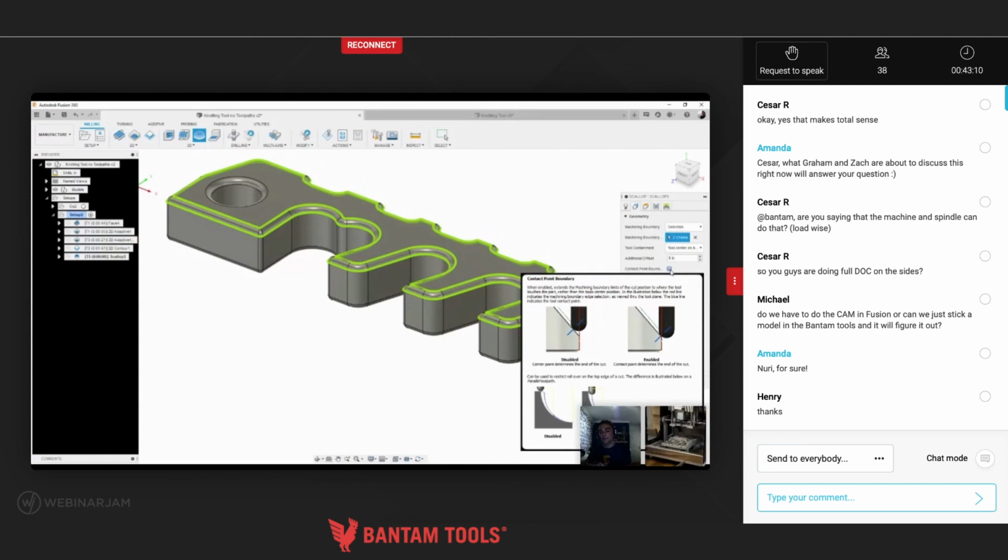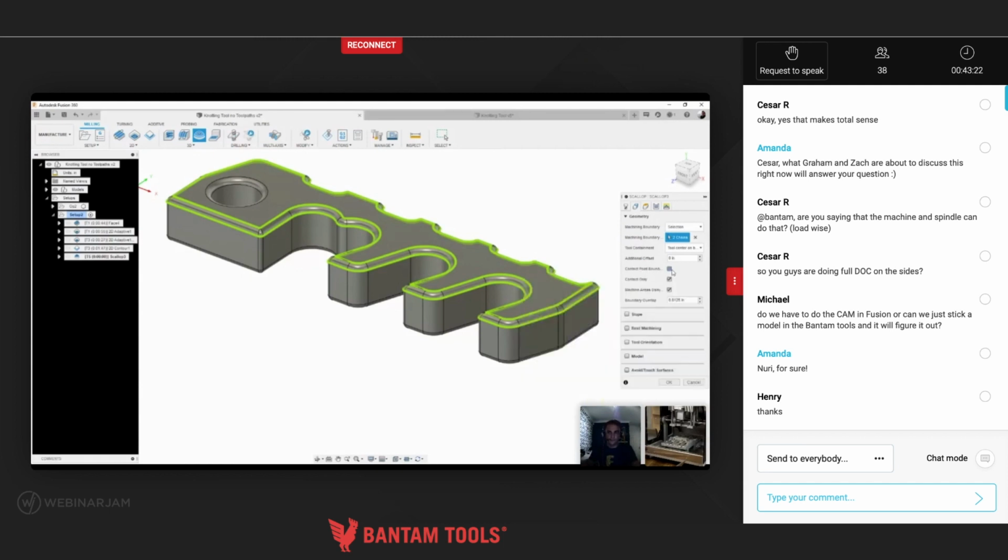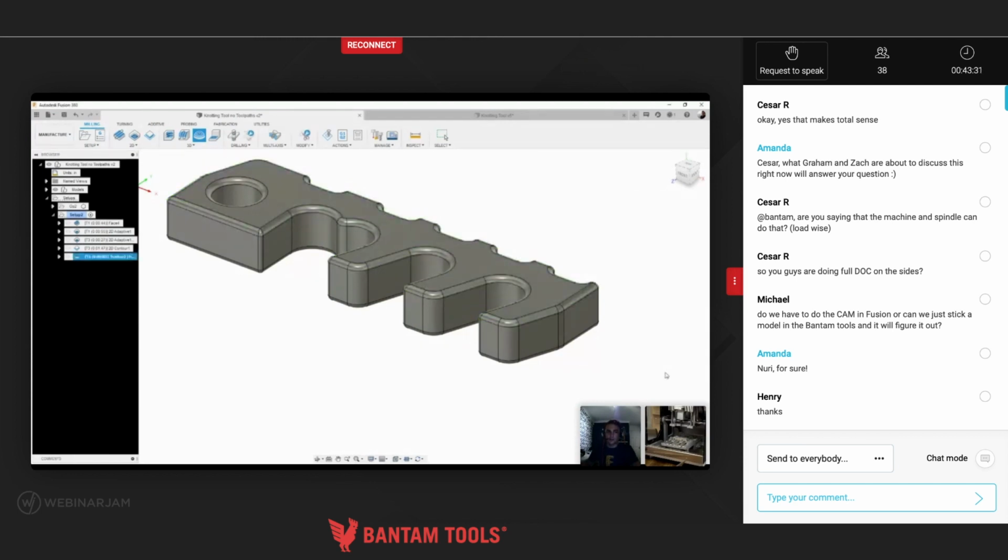You can see if I enable that, even though I've specified the same boundary, it allows the tool to go past that to make sure that we don't get those sort of hard steps on those corners. So it means the tool can flow past that and we get that nice smooth transition of the machining. So if I tick that there, it'll make sure it won't go past that point. I'm just going to show you something quickly if I press OK without doing anything else.